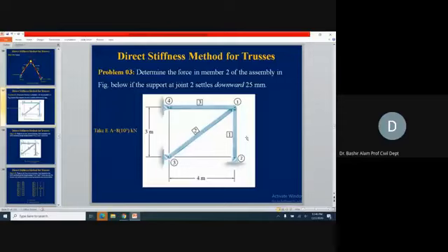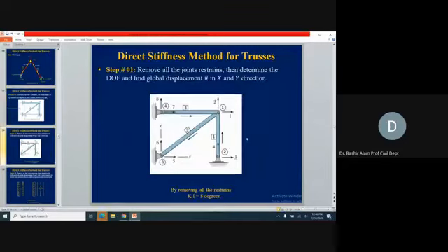So at 1, the free joint, we start from the free joint. Your element stiffness matrix, when you reduce it, will be accumulating in the top left corner of the stiffness coefficient matrix. And quickly I'll show it to you. Here, according to this, you go by this connectivity. Member 1, you see horizontal and vertical 1, 2. Member 2, 3, 4. Member 3, 5 and 6. Member 4, 7 and 8 displacements. Connectivity you can see with these arrows.